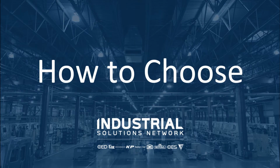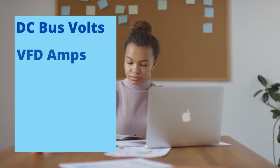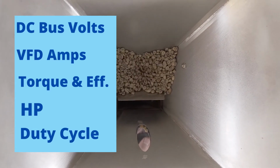How to choose a dynamic brake. To select a dynamic brake, you'll need the following pieces of information: the VFD's DC bus voltage trip level, the VFD's full load amps, the motor braking torque and efficiency, the VFD's horsepower, and the system's duty cycle.